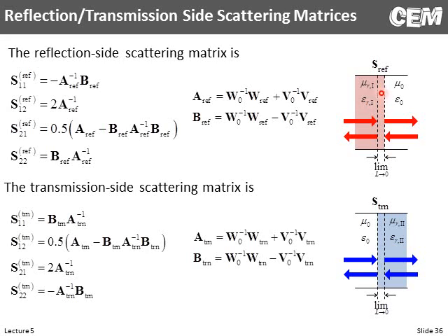And for the middle, we're free to either put in mu and epsilon or mu naught epsilon naught. That would work. But what we absolutely have to do is make the thickness of that region 0. Otherwise, the modes we would calculate would have extra phase in them, which could change the answer a little bit. So putting this in our original general framework for calculating the scattering parameters, everything reduces down to this.